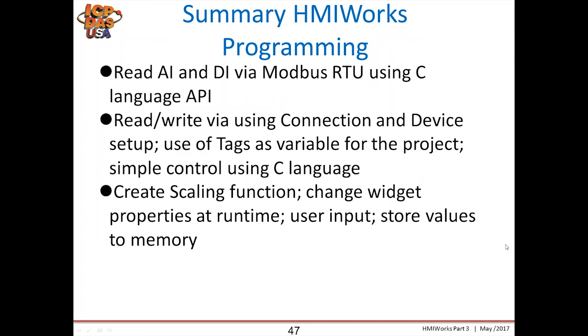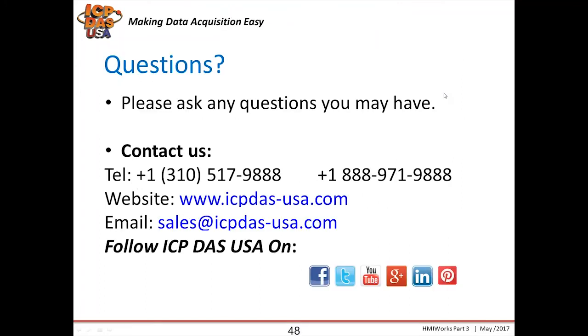In today's webinar, we have learned how to read AI and DI via Modbus RTU using C language API, how to read and write using connection and device setup, use of text available for the touchpad project, also how to create a scaling function, change feature properties at runtime, read user input and store values to memory using C language.